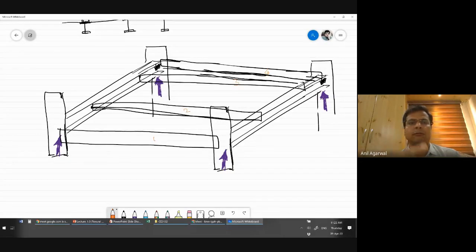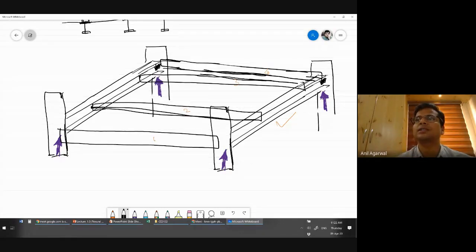Now, the vertical supports to the beams that we are interested in. We are interested in looking at the behavior of these two beams, right? We want to know the capacity of these two beams. The vertical supports are available only at the columns. What happens at the intermediate level is that at the locations where beams 2 and 3 meet the beams of our interest, the load is getting transferred to the beam of our interest rather than providing vertical support, right?